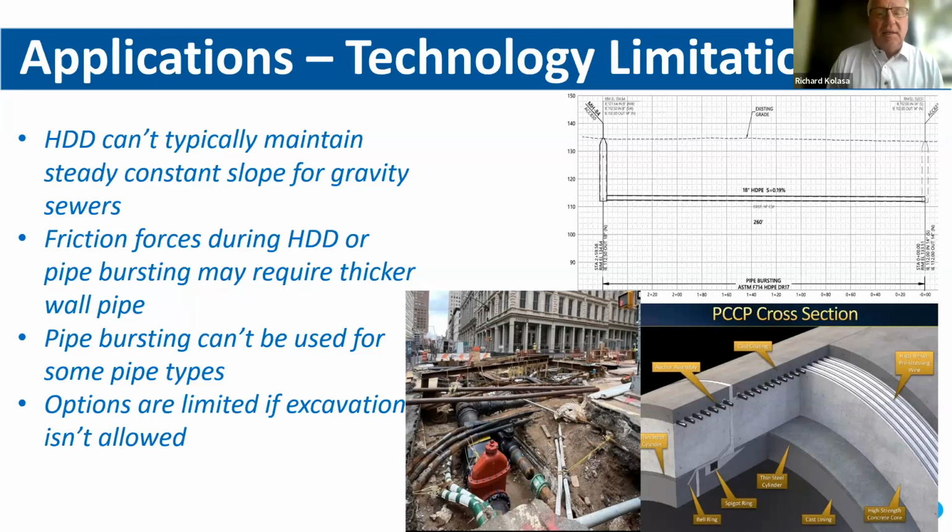Yeah, exactly. Our pressure rating is based on the heavier wall we have: the lower the DR number, the higher the pressure rating. So it's based on our thickness. It's the ability to hold hoop stress at the nominal wall thickness, and that's really what it's based on. So our DR 17s, 21s, 11s, 9s, 7.3s, in the oil business it's very typical to get up to that 300 PSI type number. So the thicker the pipe, the higher the pressure rating.